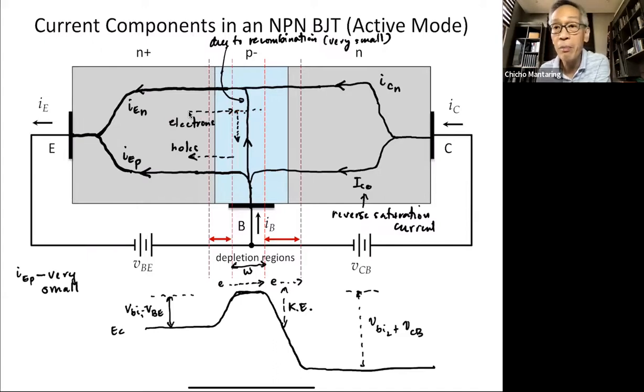That is the basic carrier action here. Now, if this were a PNP, ang PNP, then you call this your majority carrier now, no? Your electron. In a PNP, the bulk of your current will now be due to holes. Because this is going to be P-type, this is going to be N, this is going to be P. So it's going to be holes now that will diffuse across the base, okay? And then some will be recombined, but the other will be swept toward the collector, and then the collector will collect these holes. So ganun yung action sa PNP. And then the direction of current is going to be to the right because the holes are positive charges or equivalent to positive charges. And so your current is in the same direction as the flow of your holes. But otherwise all of the current components will be similar.